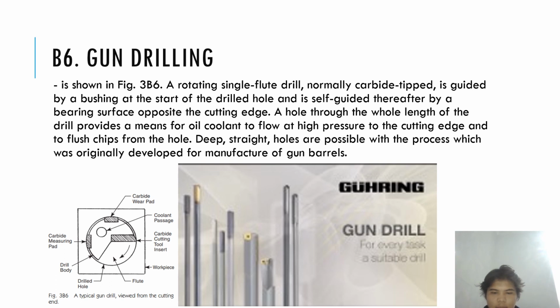Deep holes can be drilled conventionally on a CNC machining center, MC for short. For a hole to be drilled precisely, a pilot hole is required. First, the surface of the workpiece should be machined perpendicular to the hole center line. Then, a pilot hole has to be made for startup to a drilling depth of 3 times the hole diameter. This ensures that the gun drill is guided during startup.